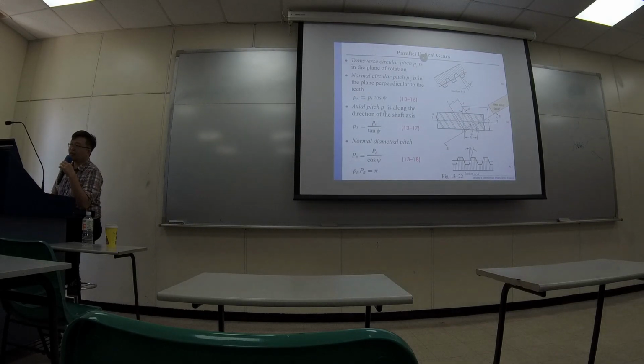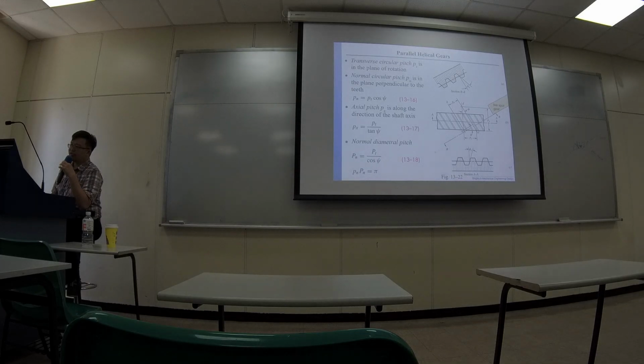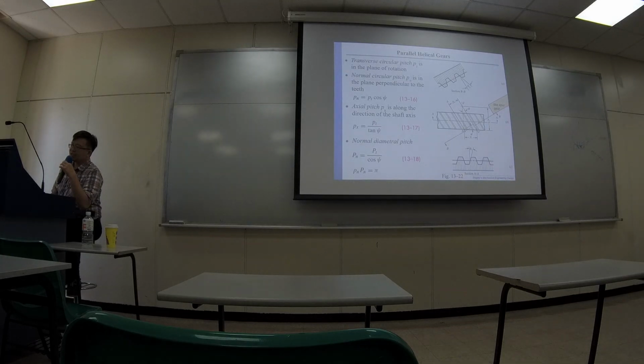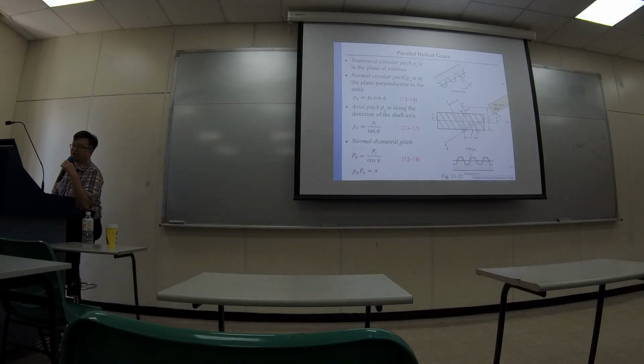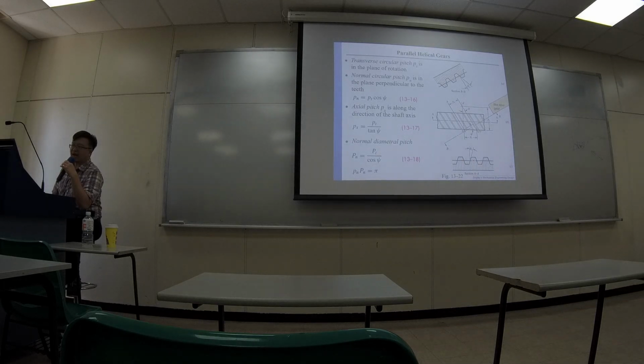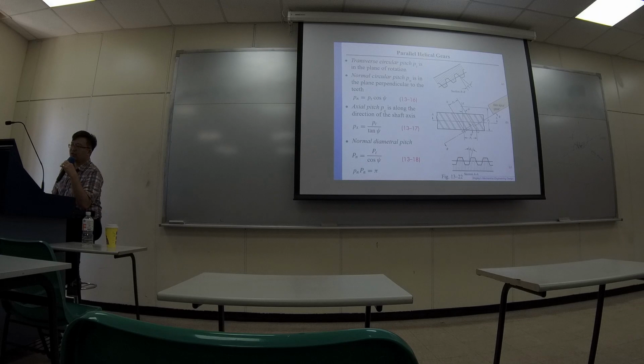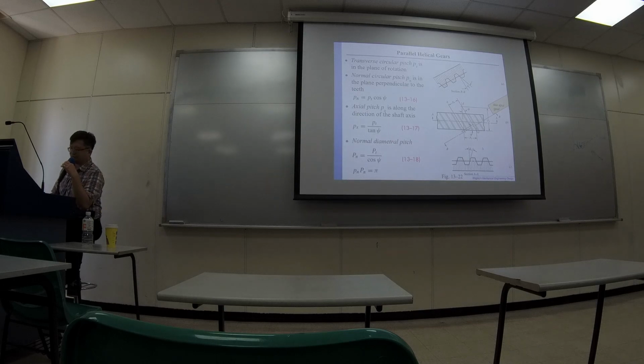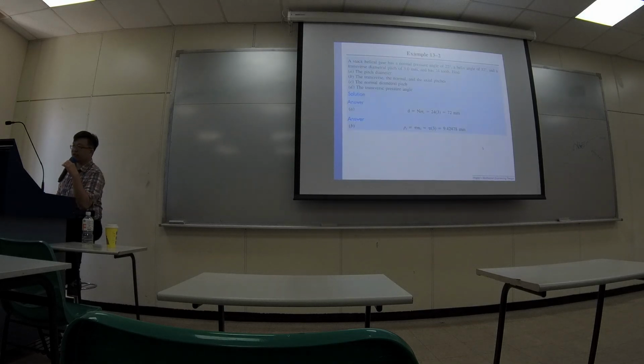Similarly, for the helical gears, if you stay on this tilted direction, the teeth behave just like a spur gear. So for whatever calculation along this tilted angle, this helical tilt, you can use whatever equation you had for the spur gear along this direction. So that's how they compute some of the equations from different directions. Okay, let's quickly move on.